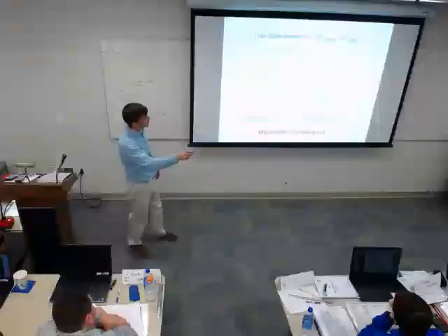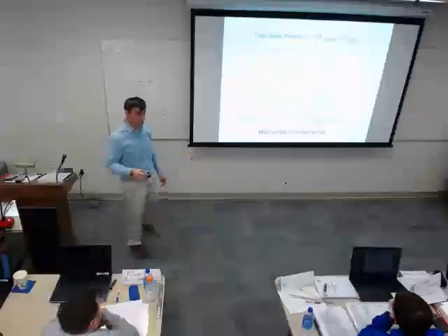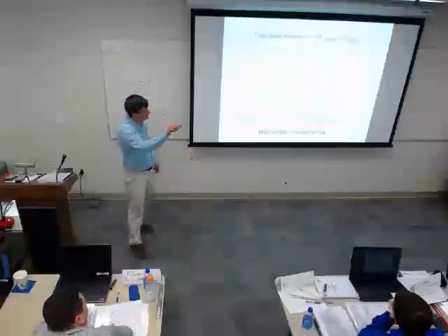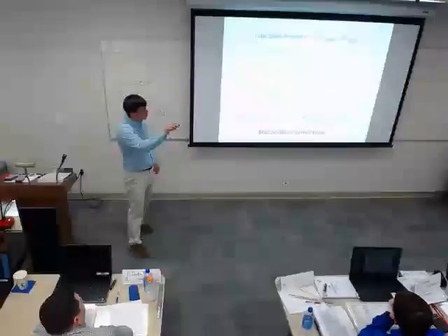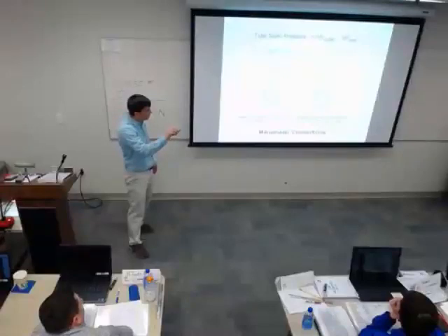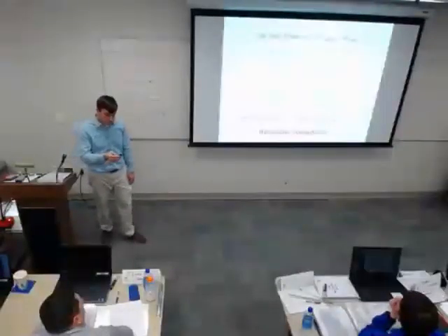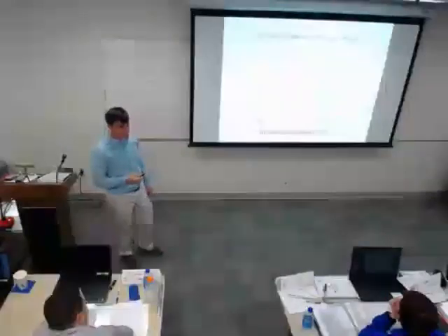And over here, if I'm on the positive side, I'll get it up on the high side. And this pressure is more than atmosphere. It's going to push that water column down. This pressure is lower than atmosphere, so atmosphere will push the water column down there. Good with that? Yes? No? Yeah.